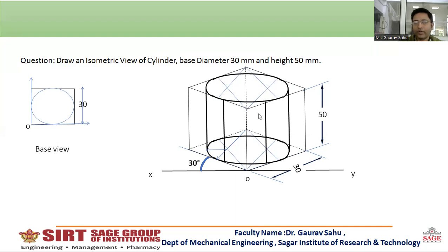Only the fundamental of drawing the sphere is different, which I will continue in the next lecture. The pyramid and prism are easy compared to drawing the cylinder. Why? Because the prism and pyramid follow the mapping method of the base rather than a conceptual method like the circle. So this is all about today's lecture, and thank you very much.